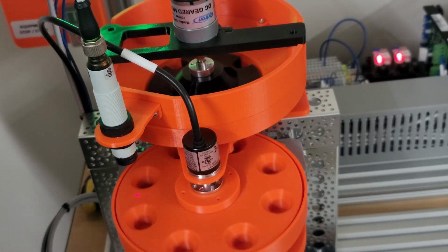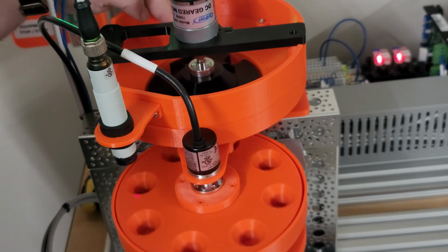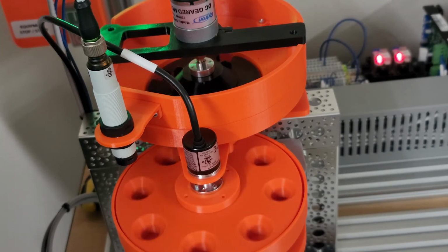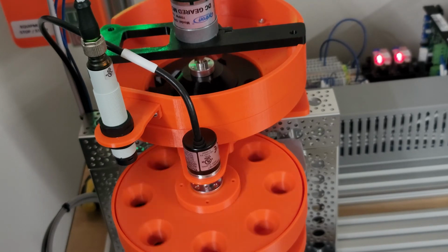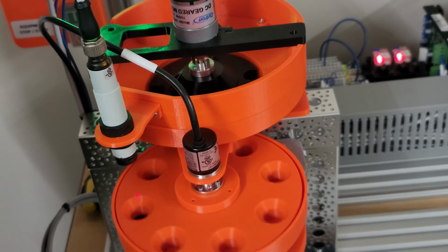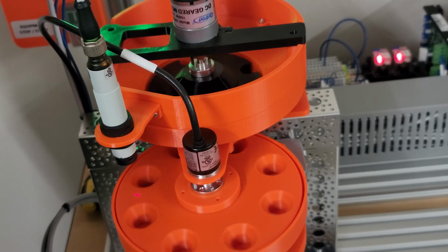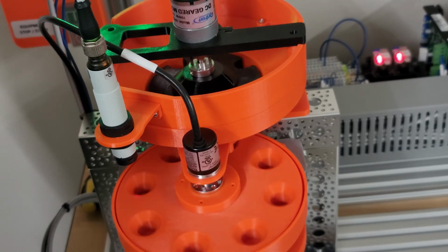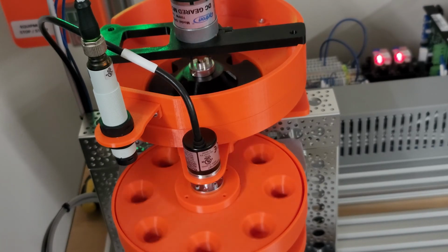Also, one thing that's potentially a little concerning, our indexer might be a little slow for our proximity sensor. We will probably have to adjust that timer, because if you remember yesterday, I set that to about 1 second, because the speed we were running at the time was making enough pulses within 1 second to reset the timer in a reasonable time frame.